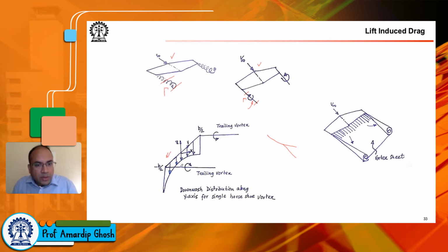Okay, so you have these vortex filaments and there is a circulation. This circulation creates a velocity field which actually produces a span-wise flow as well as a flow that is normal to the velocity vector. Okay, so you have a span-wise distribution of this W component, rather WZ,